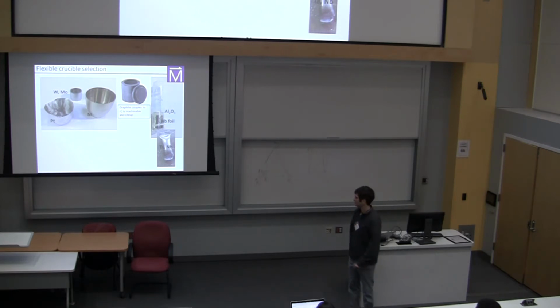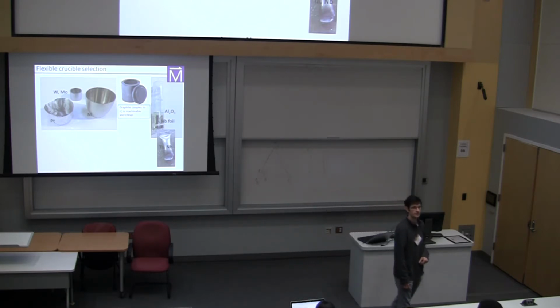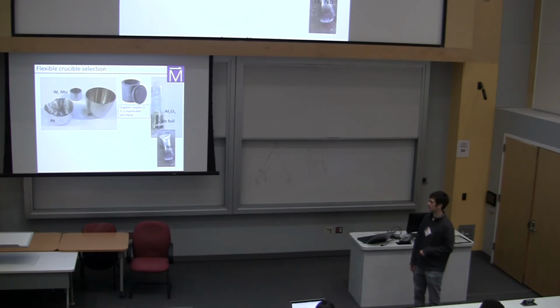So that is a really cheap and easy alternative to trying to seal these sorts of refractory metal crucibles. What is the maximum temperature it can withstand? The maximum temperature for graphite? Yeah. Well, the question you really want to ask yourself is what does the binary phase diagram look like for the carbon plus whatever you're trying to react.